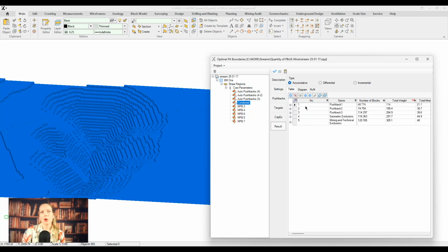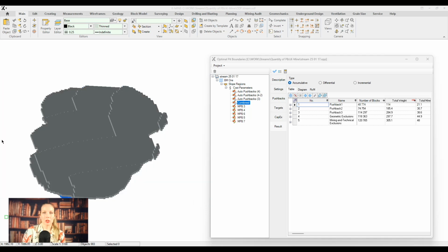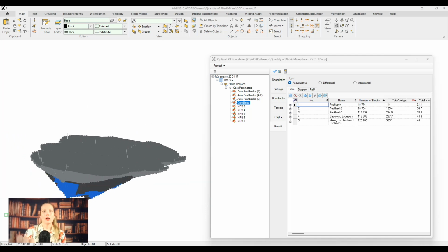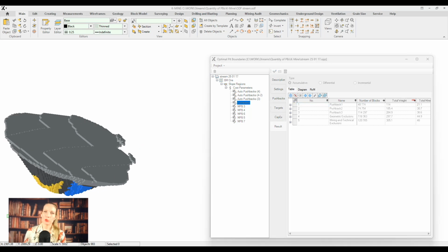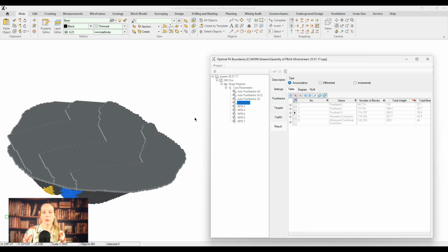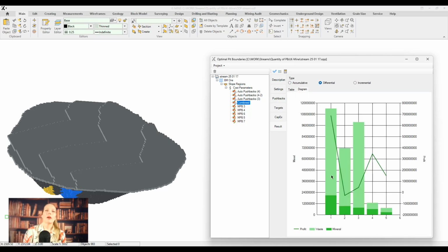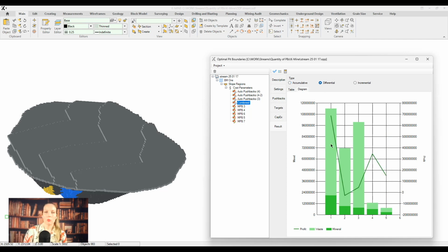For example, within the pushback restrictions, you might specify one of the wireframes that show the optimization calculation result. Then you set the target parameters for finding all subsequent pushbacks, and the calculation kicks off once you start building the second pushback, with the first one being set according to your restrictions. So you see that out of 3 pushbacks, 2 were automatically generated and 1 was manually set using a wireframe.